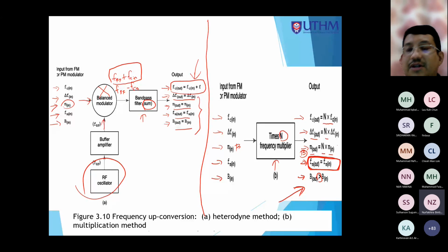Okay, this is the modulating signal, because the modulating signal input is far in the previous process. Okay, it is the input to the transmitter, actually. Because this happens within the transmitter's system, where we have already done the narrowband modulation. We have done the indirect FM modulation. Then we insert it into the frequency multiplier. So in this case, the input signal does not affect this process.